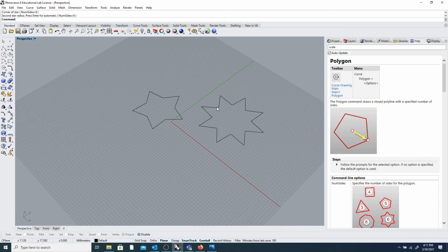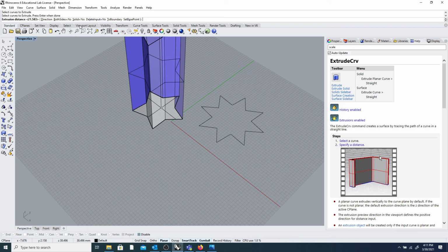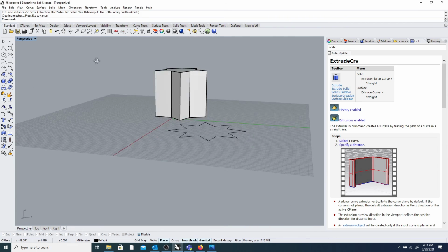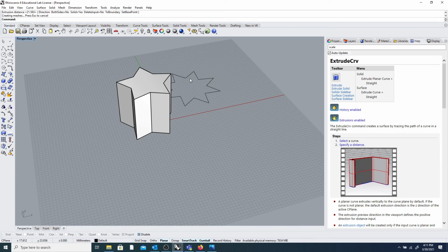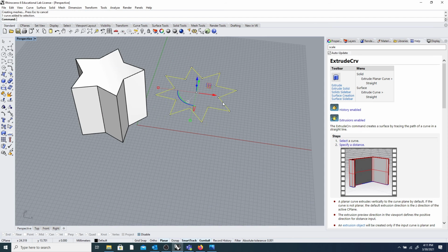So I believe the first one, we're just extruding the curve, right? And solid, yes, is checked, right? So that'll give me a solid object, just like it said it would. So on your curve that you extruded that from, is it closed?